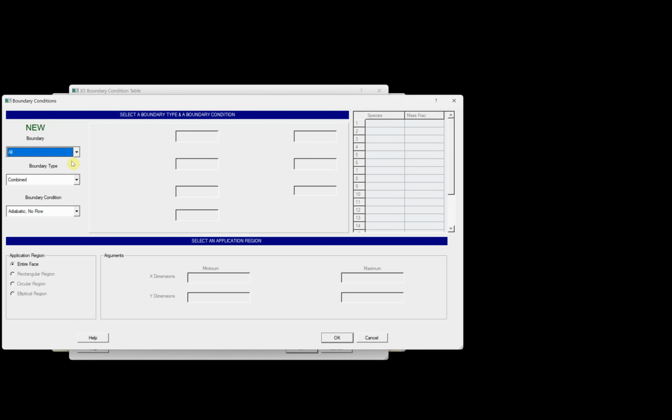Remember, there's a ground surface there, so it won't come in everywhere. It'll only come in through the hole. Now we're going to add the species boundary condition at Z min so that it's coming in as dodecane vapor. It's species and mass fraction. So this will be 1 and all the others will be 0.